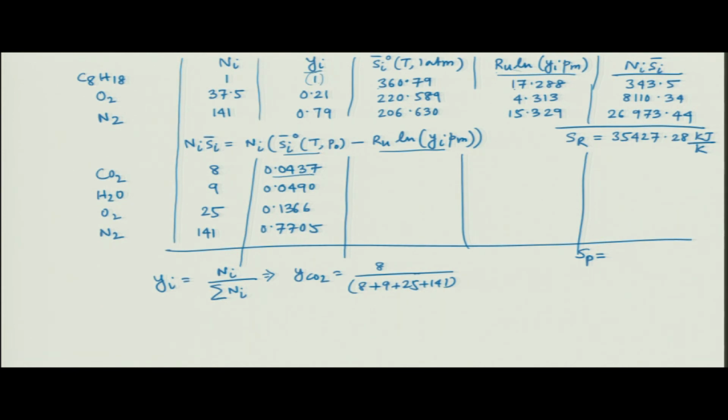So, that is the mole fraction. Now, from the table you can find the entropy of these species at the temperature that is given, right. So, T is equal to 950 Kelvin, where the gases are leaving the turbine. So, the temperature is 950 Kelvin where all these species are leaving the turbine. And accordingly you can find the entropy of CO2 at 950 Kelvin and 1 atmospheric pressure.